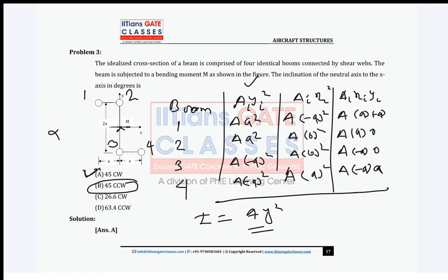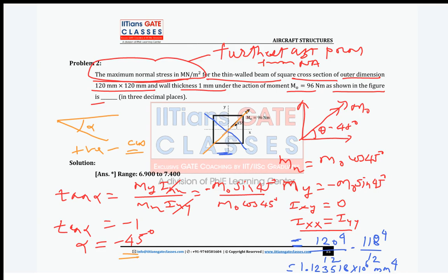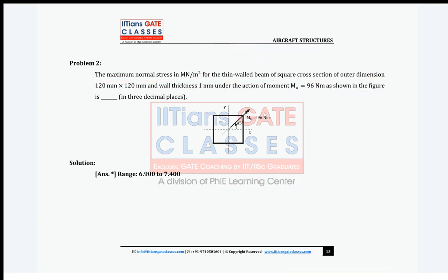Now, one thing, as I told, we will do here is finding inertia using the thin-walled assumption. Okay, so this is the section. Now in case of this, we know already, right? This is your centroid. So guys, suppose we want Ixx. For this section Ixx is directly bd cube by 12, right?